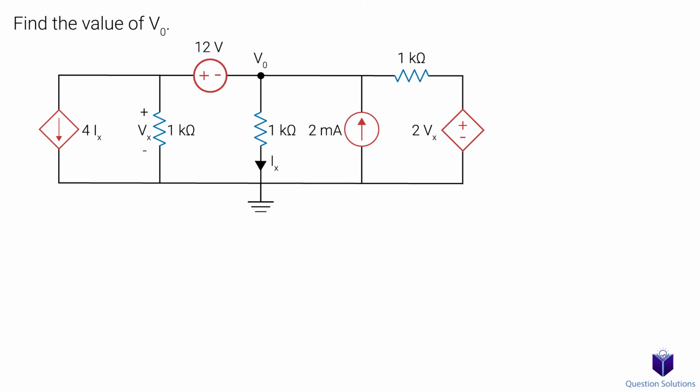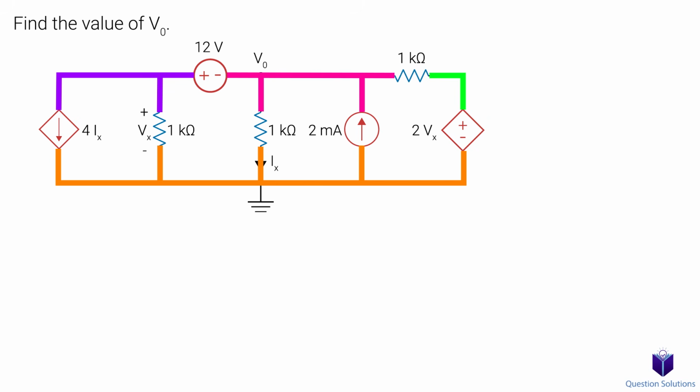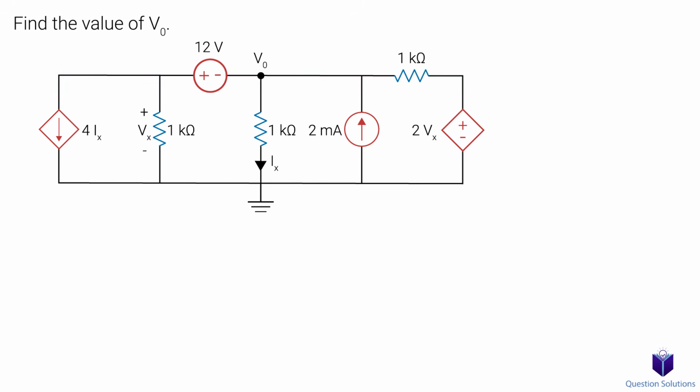Now we tackle dependent current and voltage sources. Looking at the circuit, we have 4 nodes, which means we will need 3 equations to solve it. Ground was already picked for us, so we can start labeling the rest of the nodes. Since V0 was already assigned to the top node in the question, I will label it node 0. Keep in mind, while we selected this point as node 0, all of this is still node 0.